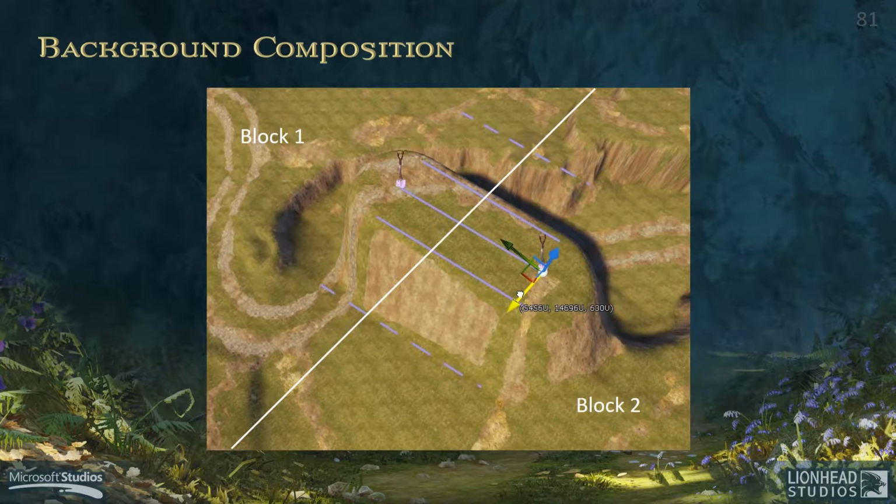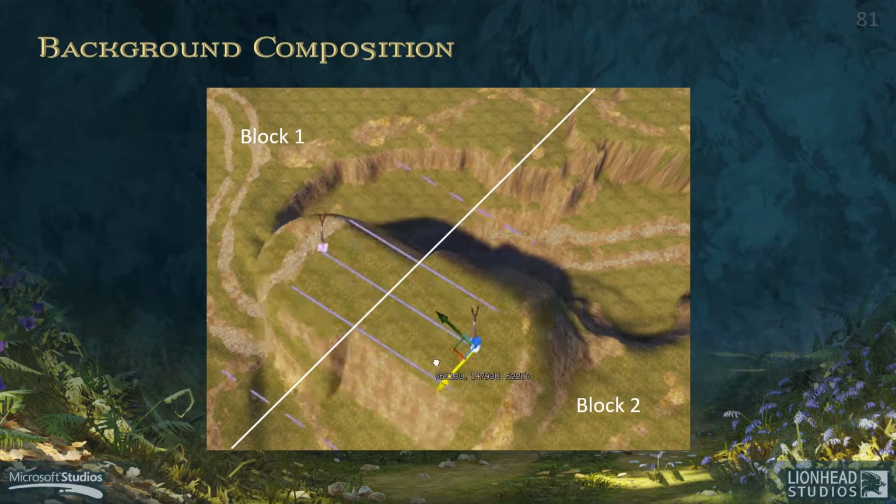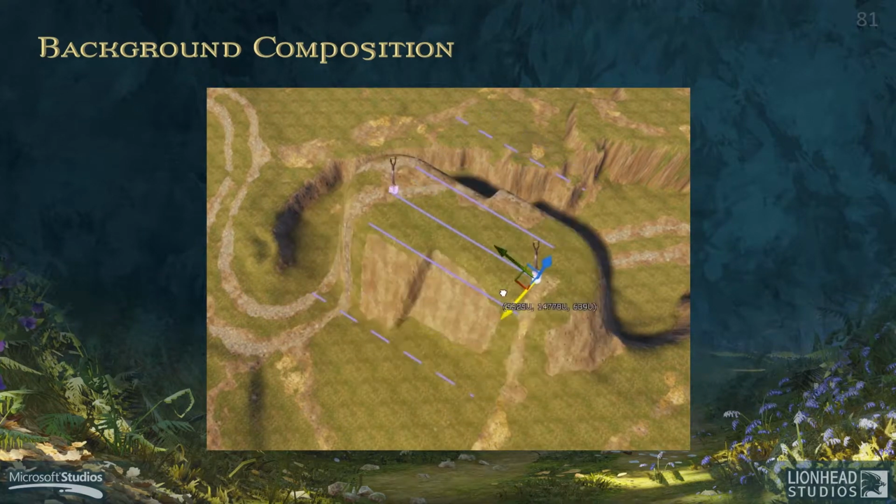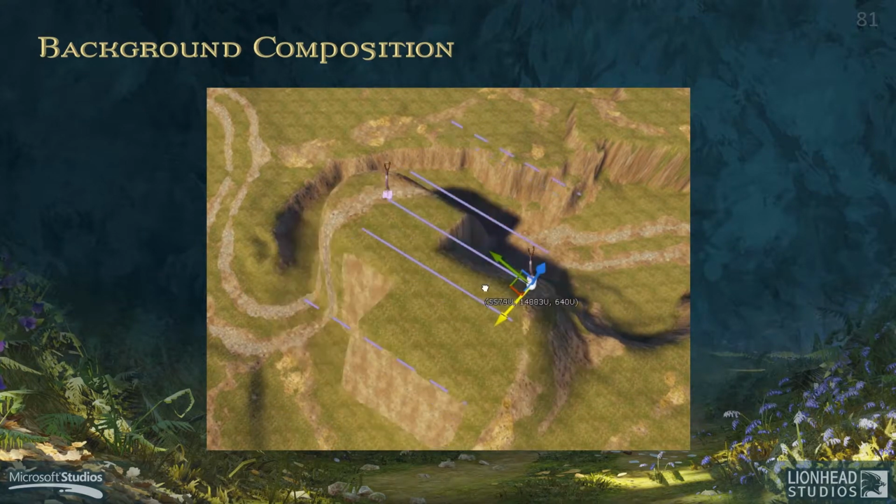The same background processes that handle the mesh position calculations for the blocks are utilized to speed up the overlay calculation and recomposition in the editor. Moving a spline invalidates blocks. Each schedules re-render of spline height effects into overlays and recomposition in the background ready for a resubmit via injection to the actual engine height material maps.